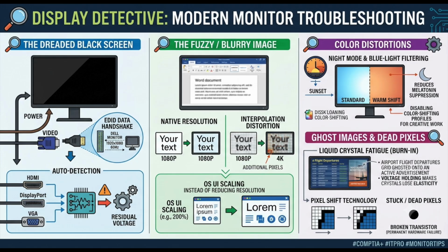Yeah, so this is a great example of smart technology creating its own problems. Monitors today are manufactured with multiple inputs to be versatile. Right, you've got HDMI, DisplayPort, maybe an old VGA port in there. Exactly. And they are programmed with firmware that constantly scans those ports, looking for voltage that indicates a live signal. But that auto-detection polling algorithm isn't flawless. It gets confused. Very easily. Sometimes the internal logic board gets tripped up by residual voltage, or it just stubbornly locks onto the last port that was used, even if you just remove that cable.